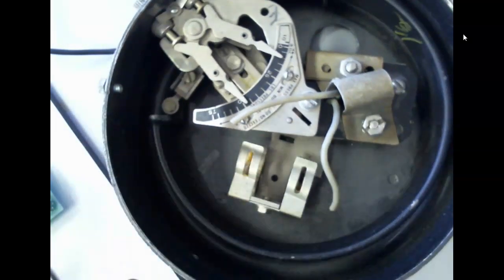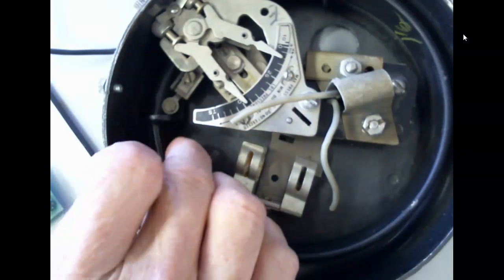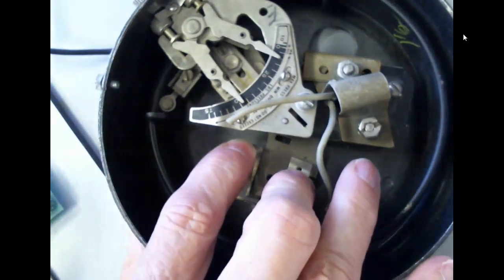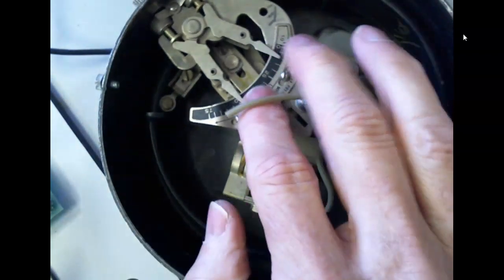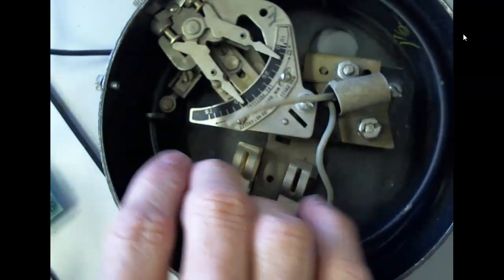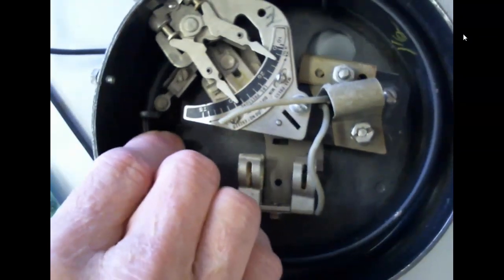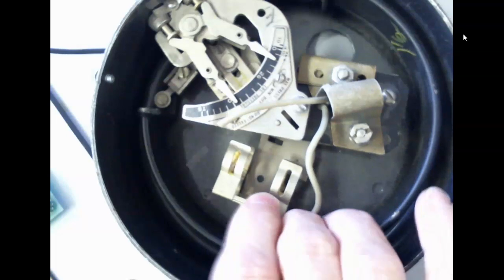This is solid metal, so this one would handle a lot of pressure. Now, this used to have a mercury switch right here, so this would give us a digital output. What you'd do is set the amount of torque you put on the bourdon tube, and then we could set what we call a span. And what's a span? A range where we could set a low pressure and a high pressure range.